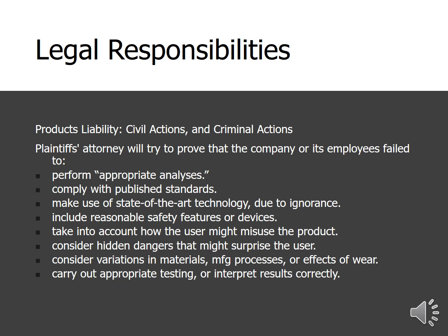The plaintiff attorney will try to prove that the company or employees failed to perform appropriate analysis, comply with the published standard, make use of state-of-the-art technology, include maintenance safety feature or device, take into account how the users might misuse the product, consider hidden dangers that might surprise the user, consider variation in material, manufacturing process, wear, carry out appropriate testing, and interpret results correctly.